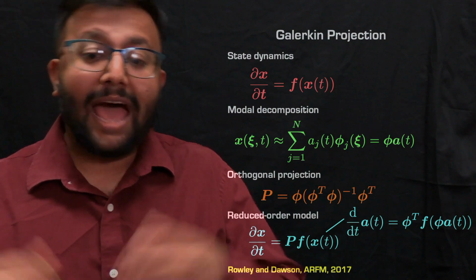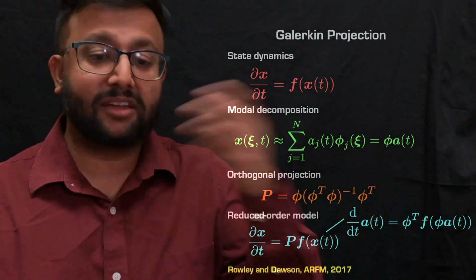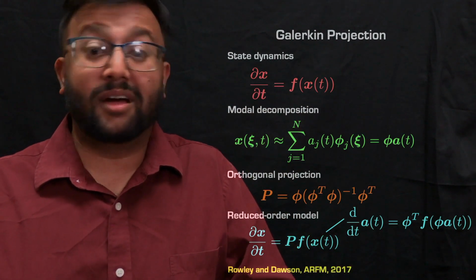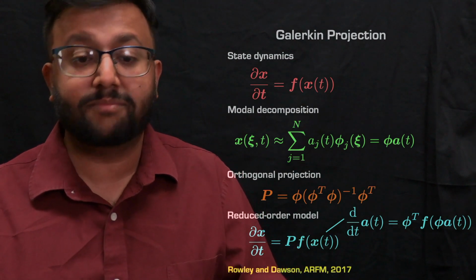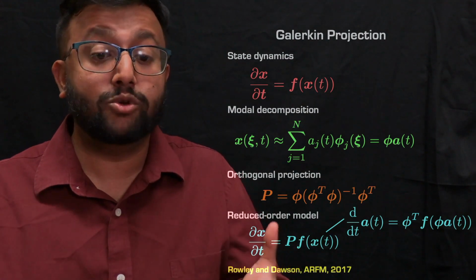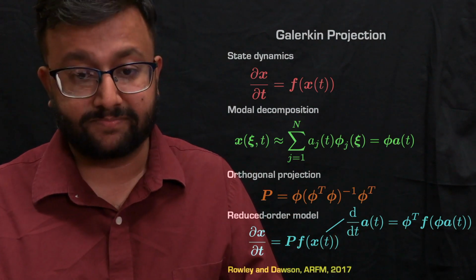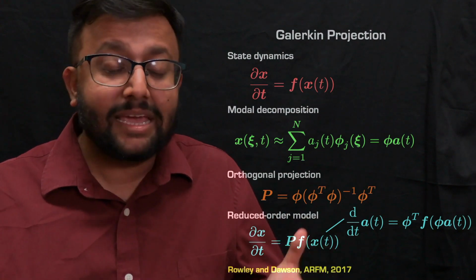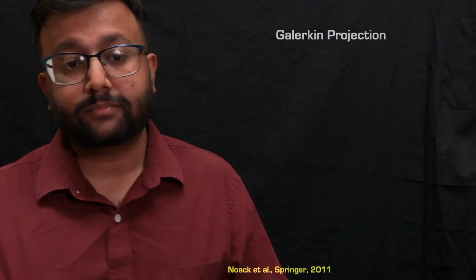So what happened is we started with a state dynamical system that governs a PDE, and we ended with a simple ODE based dynamical system that describes the evolution of the temporal coefficients of the modes, right? So this is really powerful. This technique is called Galerkin projection.